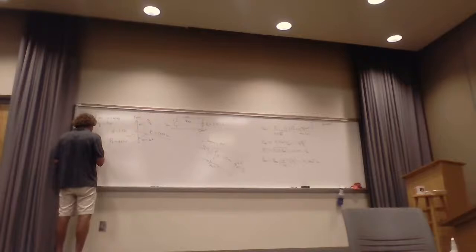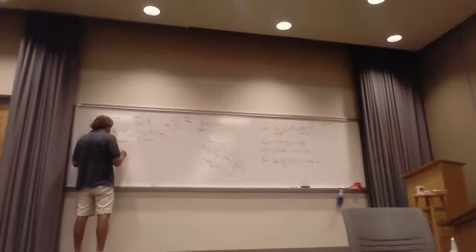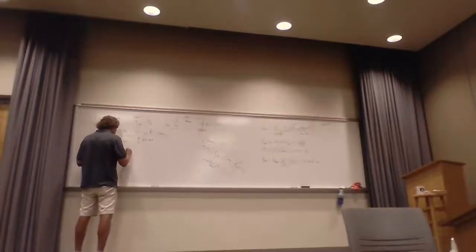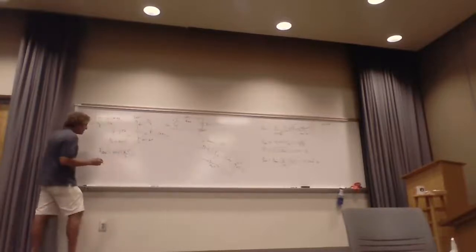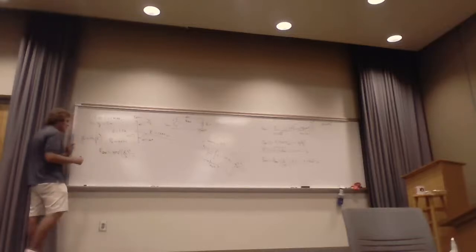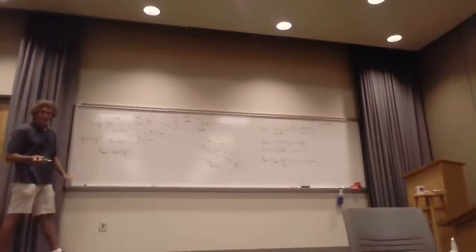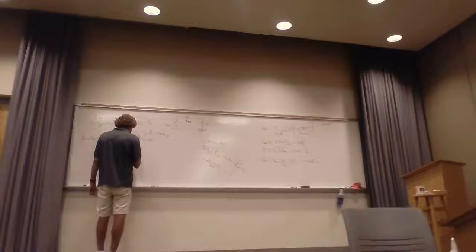And when I calculate R rad, that's again 80 pi squared L over lambda squared. Here, L over lambda is 0.15 over 3. Right? And you take that and you square it, and you're going to find it's 1.97 ohms. And then you realize what I was doing.